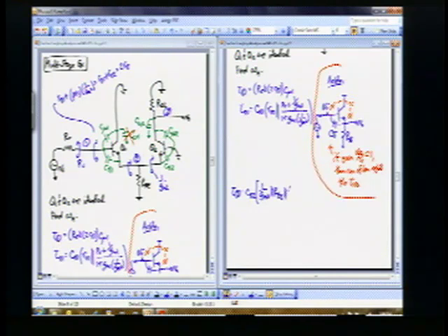Okay, except you're making the same mistake I made the first time we looked at this. Plus 1 over GM1, plus RS over beta plus 1. Exactly, plus RS over beta plus 1. Excellent, good. You guys are really picking this up. Okay, so very simply, there it is. That's the time constant for that.